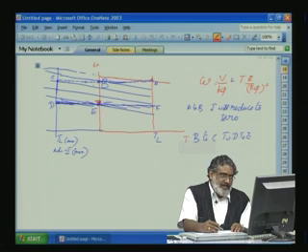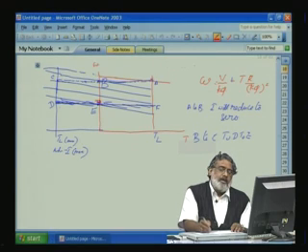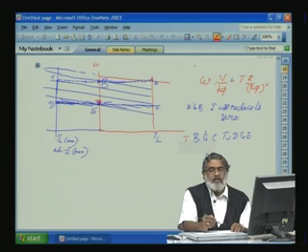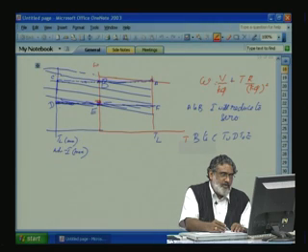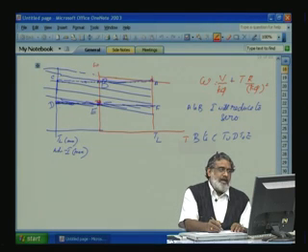A further reduction in the voltage, current will start flowing from the motor, that means due to back EMF, it will flow from the motor to the converter side. So, the equation will be like this, previously it was minus, now it will be plus. So, instead of drooping, it will slowly increase, with the same slope. So, from B to C, current is negative. So, the torque is also negative. So, quickly it will come to C.